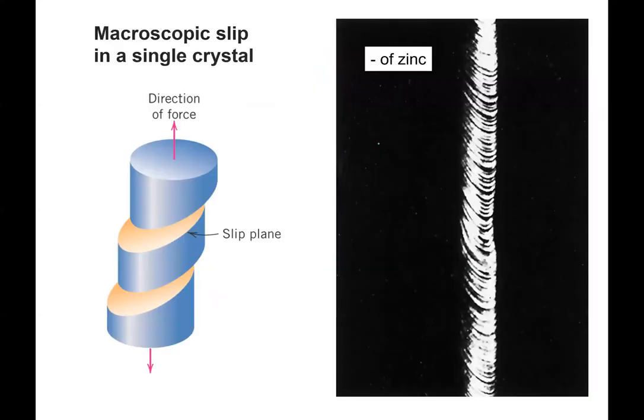All right, so this is just showing the HCP system. This is a single crystal of zinc, and it's oriented so the basal plane is just slightly off axis. And you can see now the slip all along these basal planes as they line up all down this crystal. And so that's these planes here. And so that's just neat, kind of a visual of showing this effect. You can never get this with the face-centered, no matter how you oriented it. When you pulled on that sample, it would eventually just neck down and fail. You wouldn't see these bands of deformation like this.